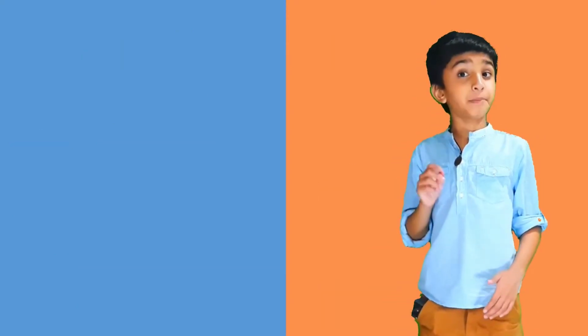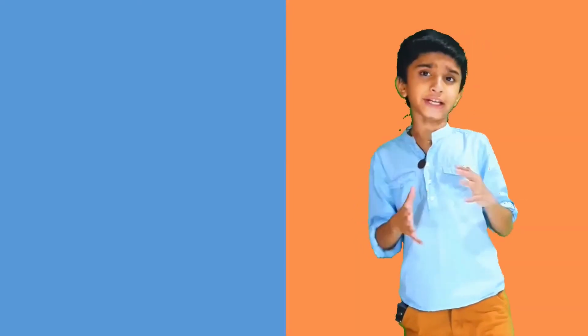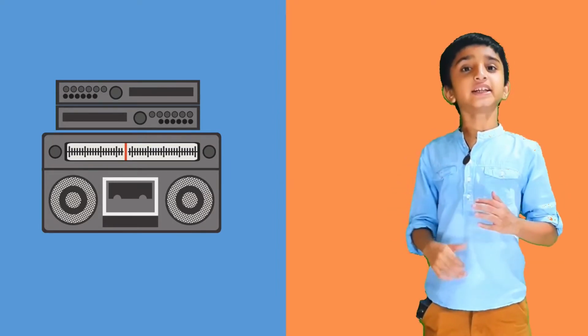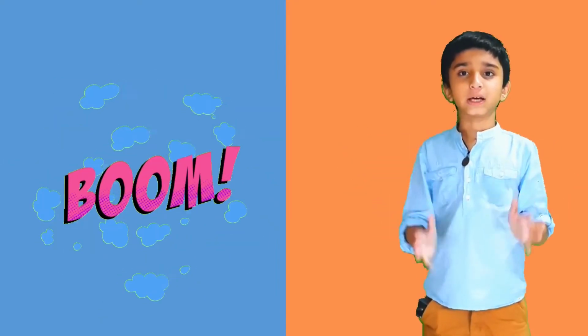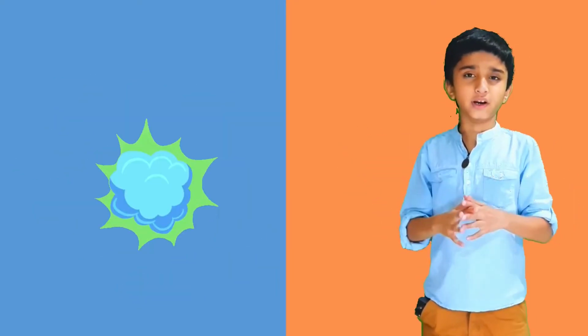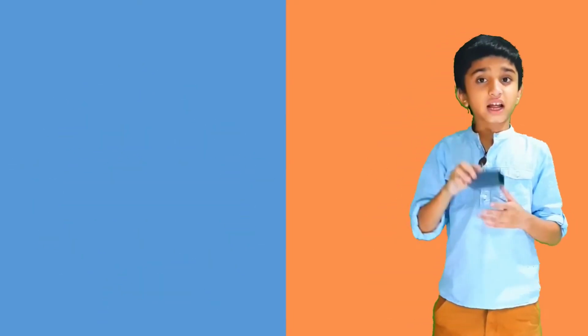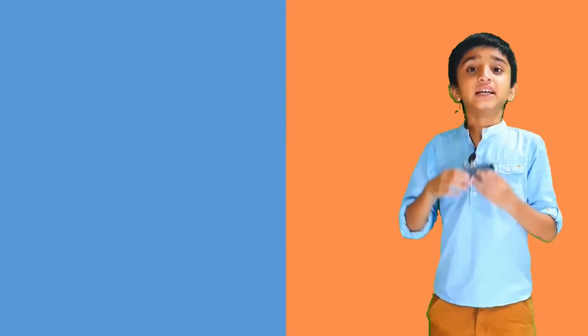Now look at the amplifier we saw in the beginning of the video. This one needs 110 volt. If I connected it in India, then poof, some smoke will come out of it and it will burn. So we need a converter like this one. The converter converts 230 volt AC to 110 volt AC.